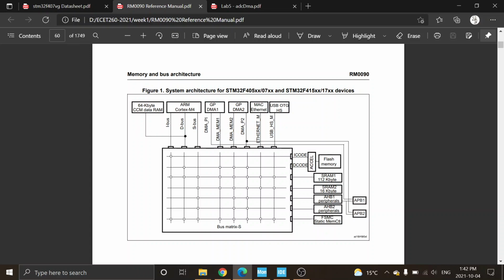And so it looks at all the different needs and what can I send where. You know, I could send the ARM Cortex out to the FSMC at the same time. DMA1 could be sending something out to one of the peripherals, as long as you're not trying to use the same bus at the same time. And again, there's this bus arbiter that says who's most important and who gets it and where it has to take turns. So another piece of silicon, again, kind of complex to set all this up and put the right thing to the right place. The graphical interface makes most of it done for you, and so that's kind of nice.